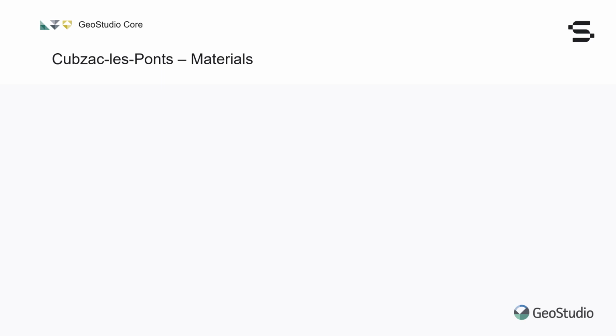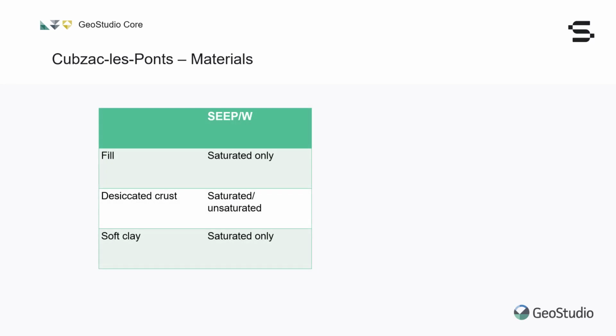For the SEEP/W analysis, the embankment fill is modeled using a saturated-only model with a large saturated hydraulic conductivity to promote drainage. The soft clay is also modeled using the saturated-only model since we expect this material to remain saturated throughout the duration of the analyses. As you will see in a few minutes, the desiccated crust must employ a saturated-unsaturated model as the water table will fluctuate within this layer during the analyses.